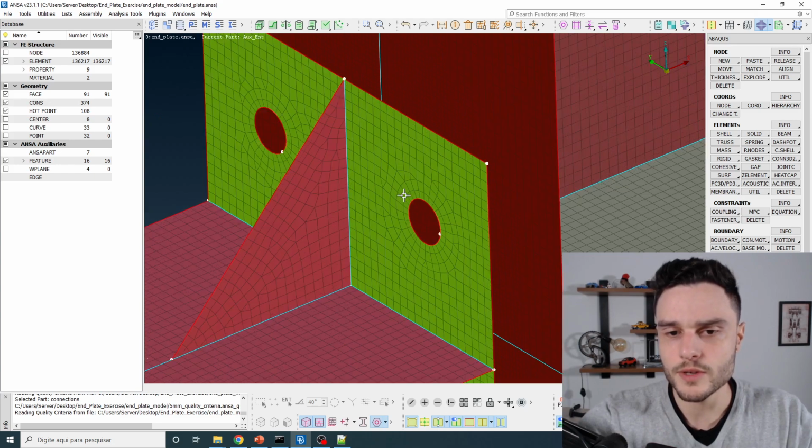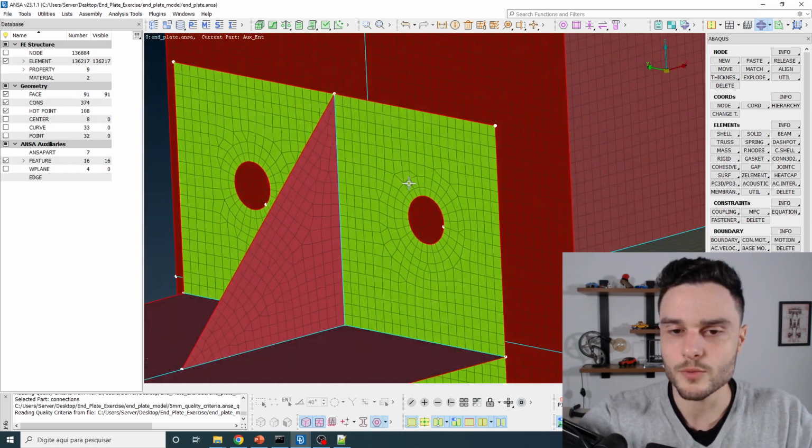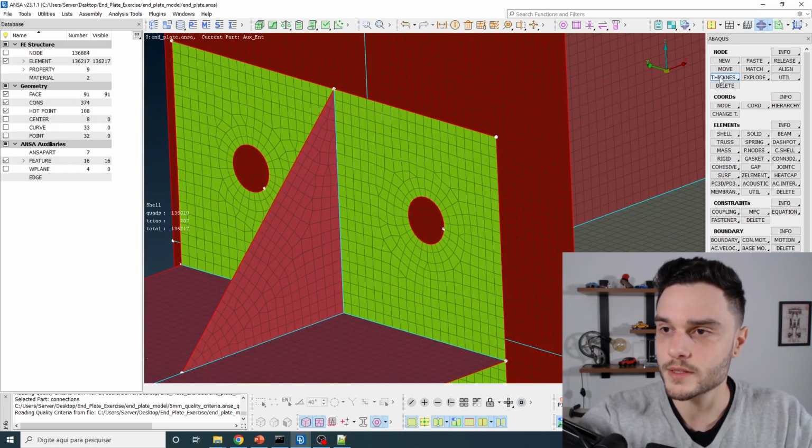But anyways, I'm going to give you an overview of how this works when we create it. So left click on coupling and hold until you see these options. And we have many ways to create it. We are going to create it by selecting nodes. So release the left mouse button when you have the mouse positioned here.